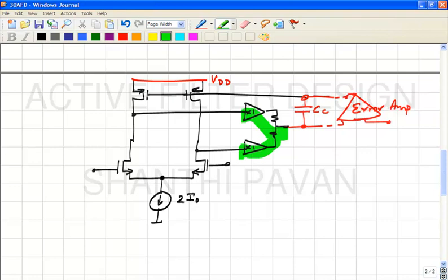Ideally, we've very nicely put x1 here, assuming that it's an ideal voltage controlled voltage source, and there's no delay there. Another thing that one needs to consider is the value of these resistors. As far as common mode equivalents are concerned, you can think of it like this, and that goes to Cc, and what is that capacitance?